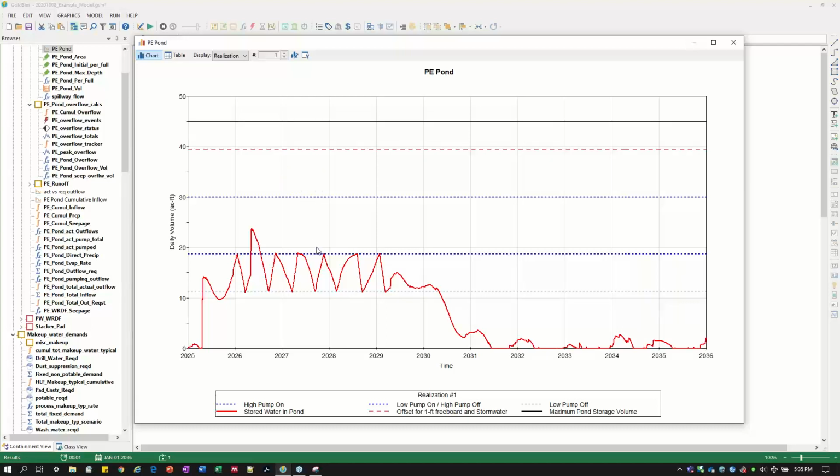And then these next 3 lines are where I have different pumps activating. In this model, this lower blue line is a low level off switch, and this next line up is my primary pump controlling operating volume. So in this example, for this peak that I'm looking at here, as soon as the water level gets above this peak, I send that information to the status element, and the status element has some additional logic attached to it that says, hey, kick the pump on.